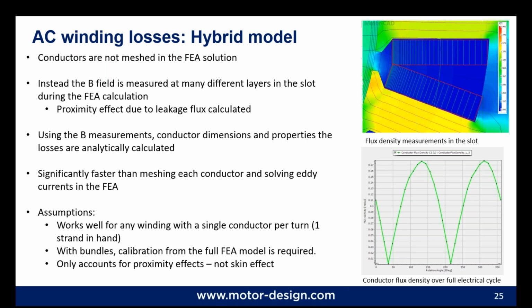And we call this the hybrid model because it still uses finite element, but it's a combination of finite element and analytical methods. So the way this works is rather than meshing the conductors in the finite element solution, we just measure the leakage flux and the flux density in the slot region during operation.